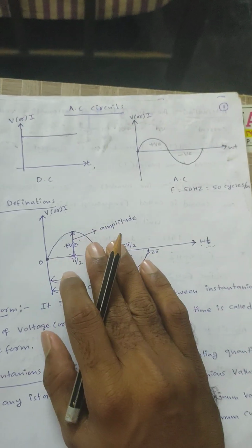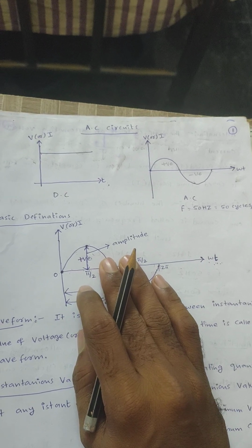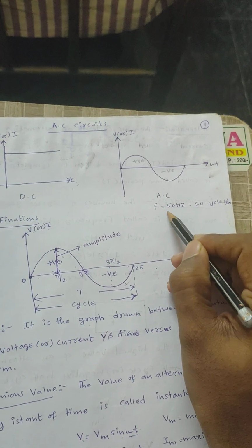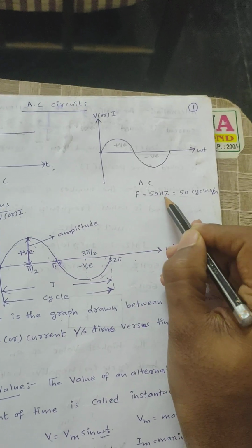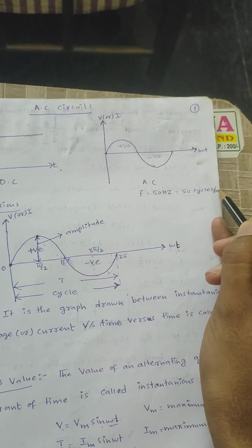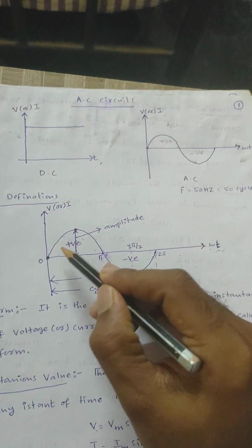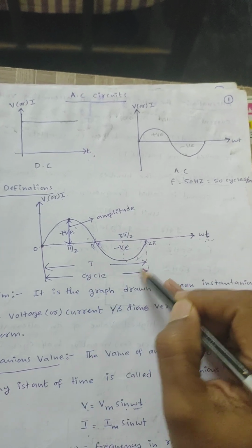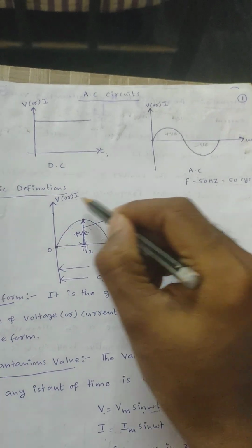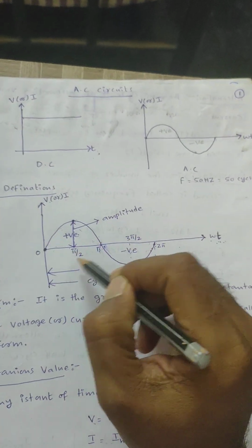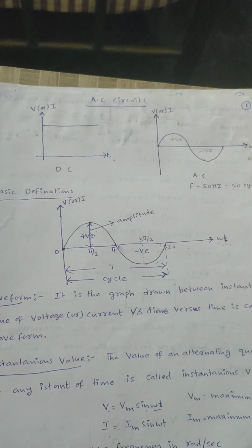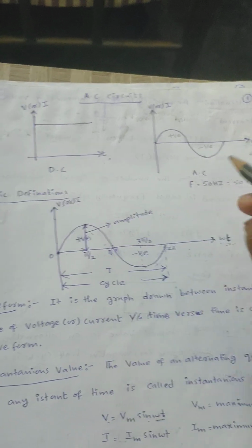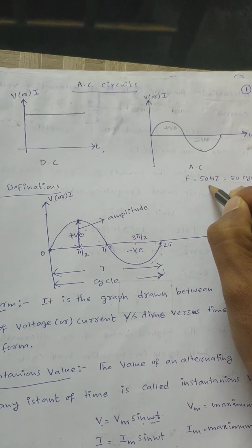That means the magnitude of voltage and current alternately changes, but practically we don't notice this change, right? The reason is frequency. The Indian standard frequency is 50 Hz, which equals 50 cycles per second. A cycle is the complete set of positive quantity and negative quantity. That means for every 1 second, 50 cycles are repeated, that is, 100 half cycles are repeated. Our eye cannot identify that variation. That is about AC voltage.